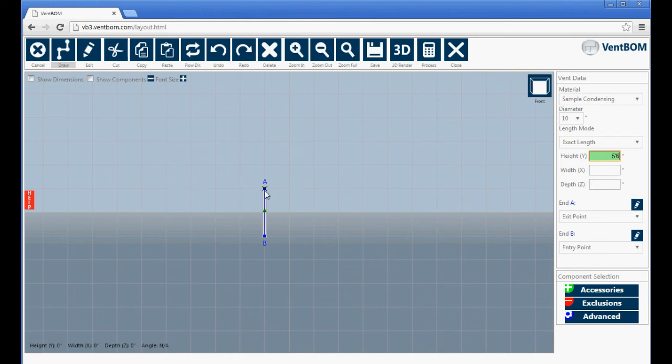Alright, this one I'm going to draw horizontally or sideways. I'm going to draw the section. As you can see, it defaults to the x-axis, so it knows that we're now going sideways. I'm going to set this one to 7 foot 2 inches.